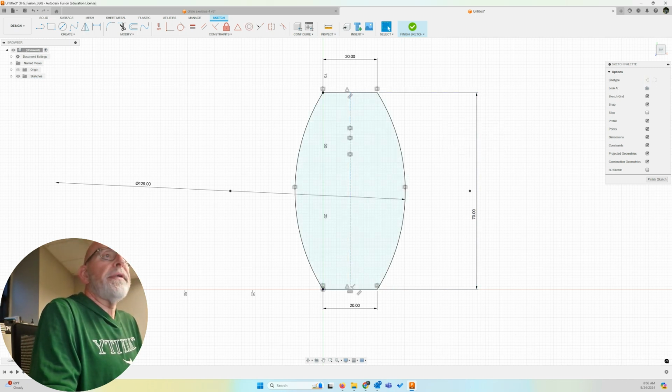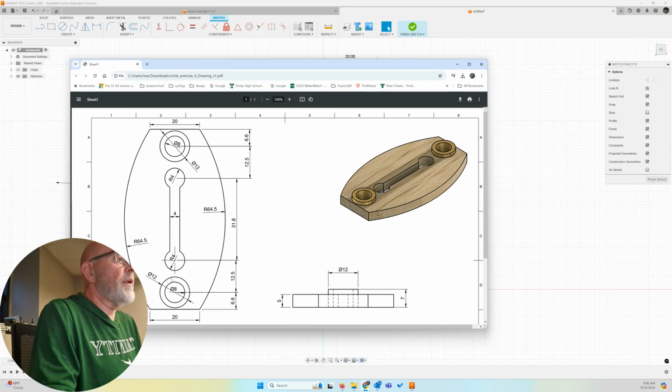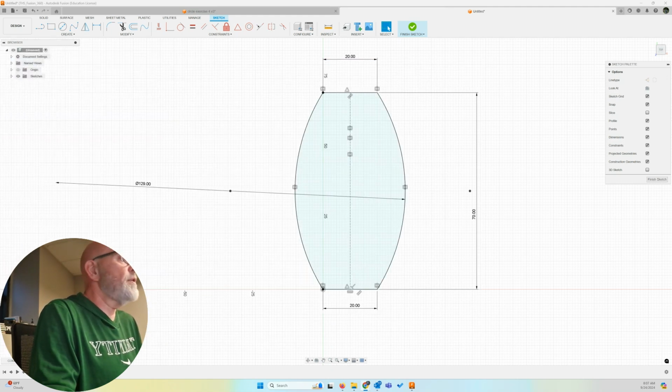All right, now let's bring up dimensions real quick. So we're going to start drawing some circles. I'm going to draw an 8 millimeter circle and then offset it by 2 millimeters to give me a 12 millimeter circle. I'll draw a couple. That'll be a couple more 8 millimeter circles. I'll position them and then a last 8 millimeters. So 4 8 millimeter center diameter circles is what we're going to start off with.